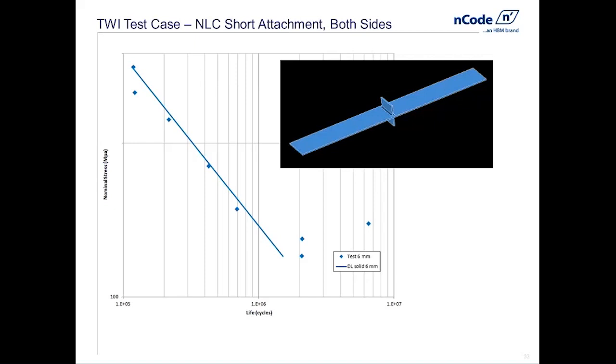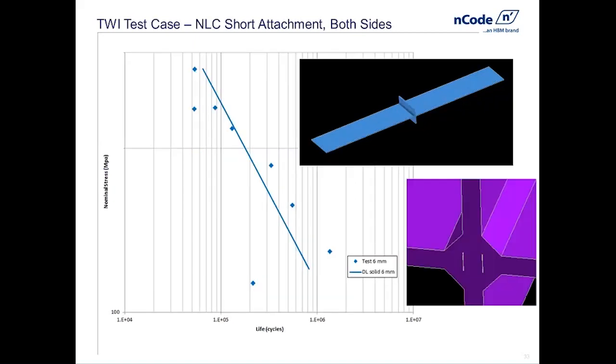Final specimen here is the actual specimen we saw earlier on, showing the ability to define paths inside of the solid weld technique. And so here, the horizontal plate is not continuous. There's two separate plates. So this is a load-carrying weld. The actual connection between those two horizontal plates is the weld itself.